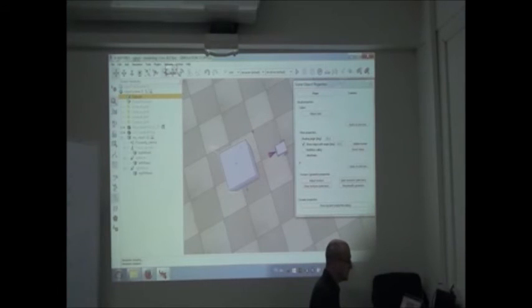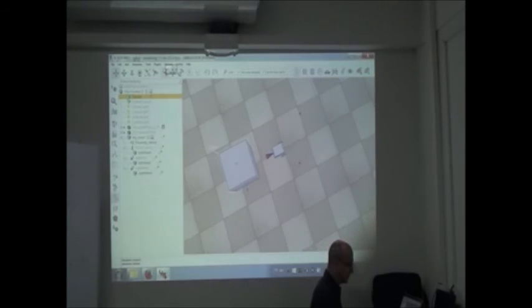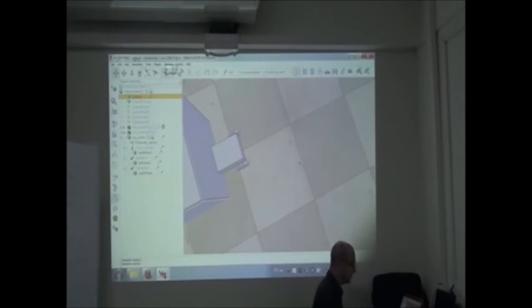So in order to make it detectable, you select the cuboid, you go to command, and here you have collidable, renderable, measurable, detectable. Just select everything so that it will be seen by the camera, it will be detected by the sonar, it will be measured and collidable also by the motion planning algorithm. Okay? And now if I press play, look, when it's going to detect it, oh, you see? Have you seen? It turned red, pink. It turned pink.